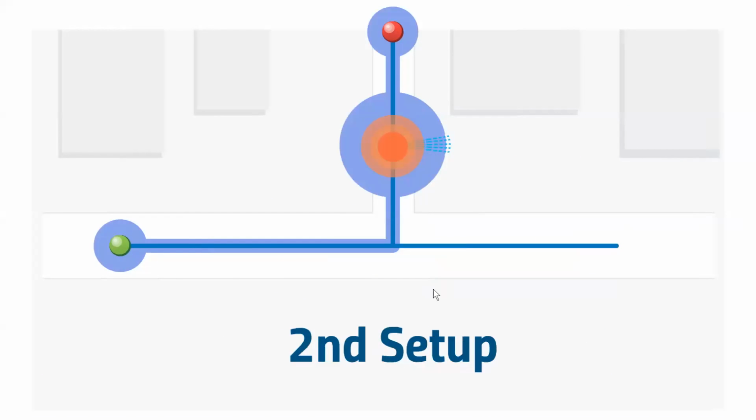In the second setup, we actually remove one of the loggers from its current position and move it down the pipe. Reposition it, run a new correlation, and now we've positioned the leak in between the two sensors. This length of pipe is no longer a straight length of pipe, but an L-shaped pipe. That's quite all right. But we've positioned the leak in between the two sensors. Now the equation and the computation of the leak is going to bring the leak back to, or position it in the exact spot where the leak is correlating.